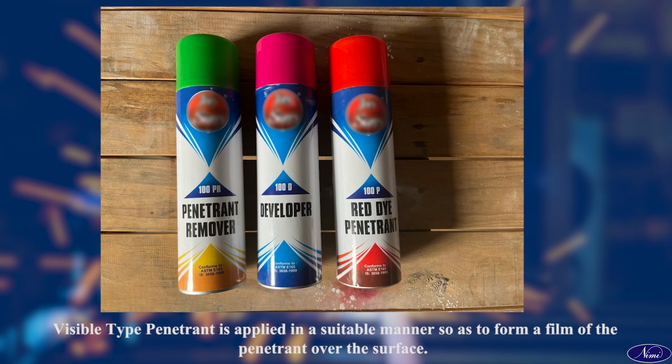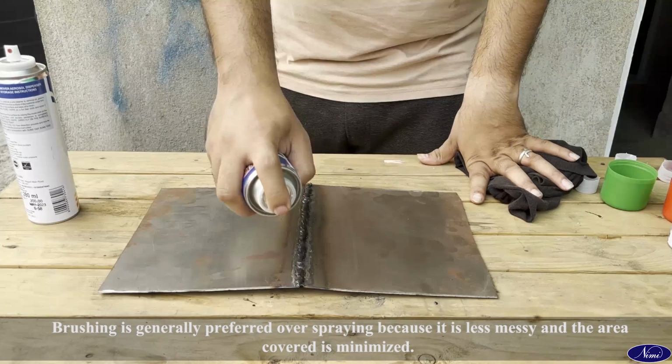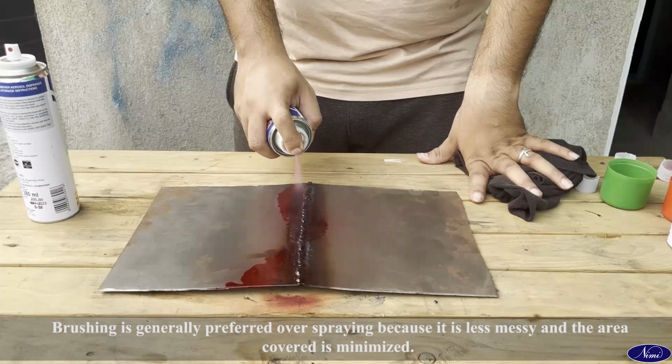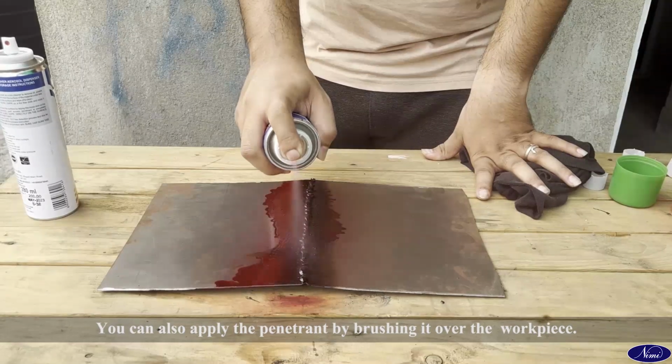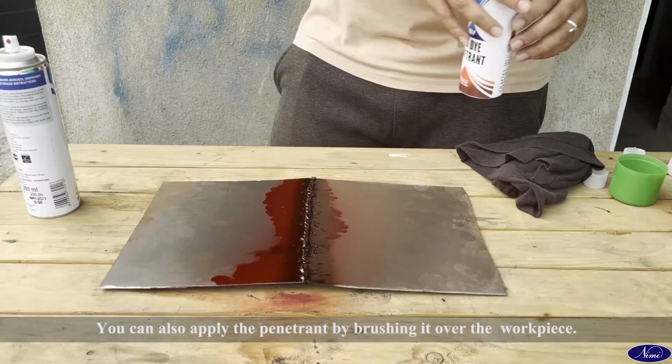Visible type penetrant is applied in a suitable manner so as to form a film of the penetrant over the surface. One can apply the penetrant in the following manner: dipping, spraying, brushing. Brushing is generally preferred over spraying because it is less messy and the area covered is minimized. You can also apply the penetrant by brushing it over the workpiece.